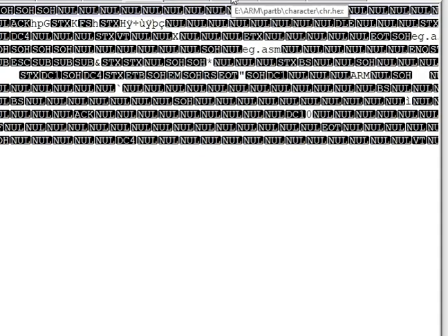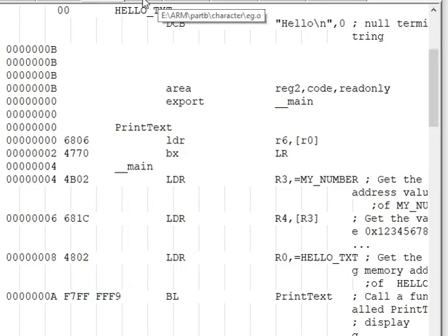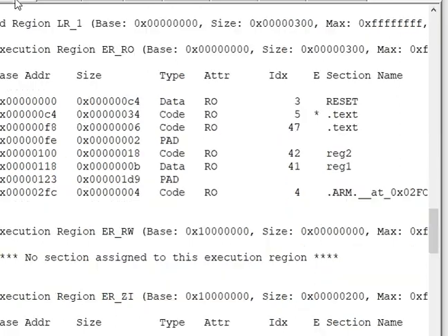Now, using your linker, you have to link this module. Along with this, there is a startup file which also gets linked together. If you look at the final absolute object file, this is the map file for your final object file. You can observe this data segment stored for the reset sequence. Reset is actually the first program which gets run. Along with that, you have a code segment, this region 2 and region 1.